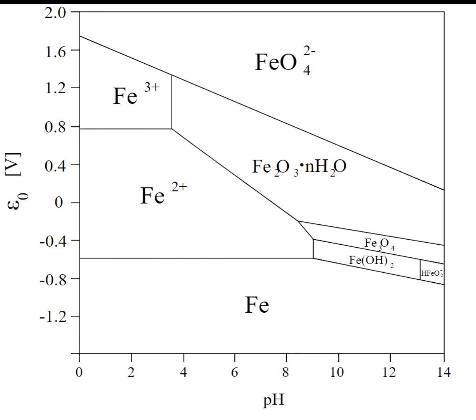As I said before, this iron oxide will be dissolving on the outside and forming on the bottom, so we'll get some current probably, but it will be limited by the dissolution process, and it will be dissolving either down here as iron 2+ or up here as this iron 3+ oxide anion. If we get past here, we will end up dissolving it faster again. So we can end up with an interesting shape of our voltage curve because we have a passive region where our iron, in this case, is covered with an oxide layer.